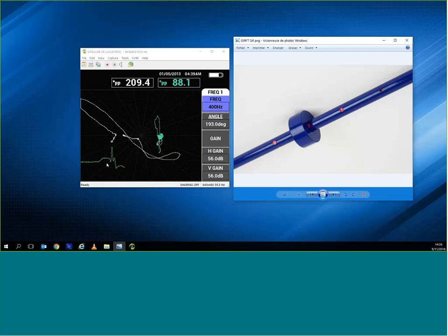So here we can see that on frequency 1 and frequency 2, we kind of have the beginning of the defect, and then it goes into the support signal. And on the mix channel, we actually see the vertical line, which is what we have calibrated to be a hole. So using, once again, remote field, the auto mix function, we're able to quickly scan and still find defects close to supports.